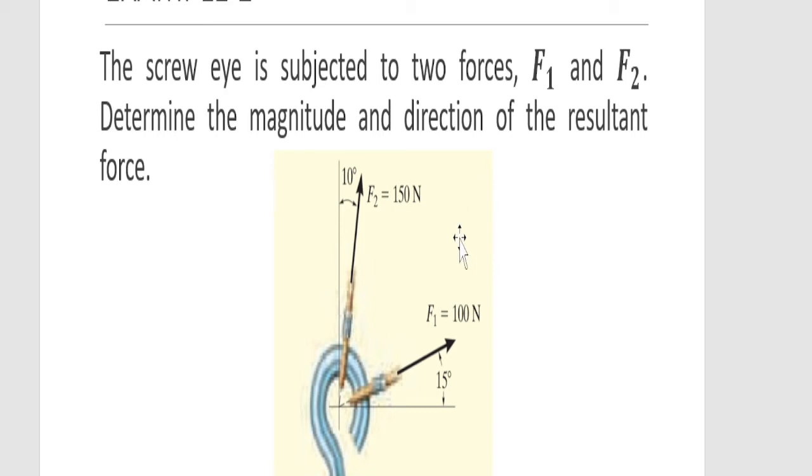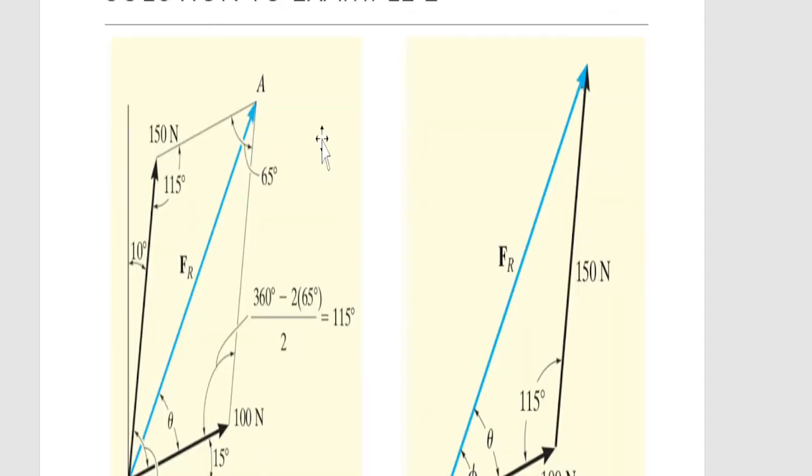So for that, basically you are going to make a free body diagram and use the parallelogram law. So you draw the parallelogram here, we can see the diagram here. You draw the parallelogram free body diagram, then the parallelogram opposite of F2. So once you have a parallelogram, you can also get the resultant vector, which will be Fr.